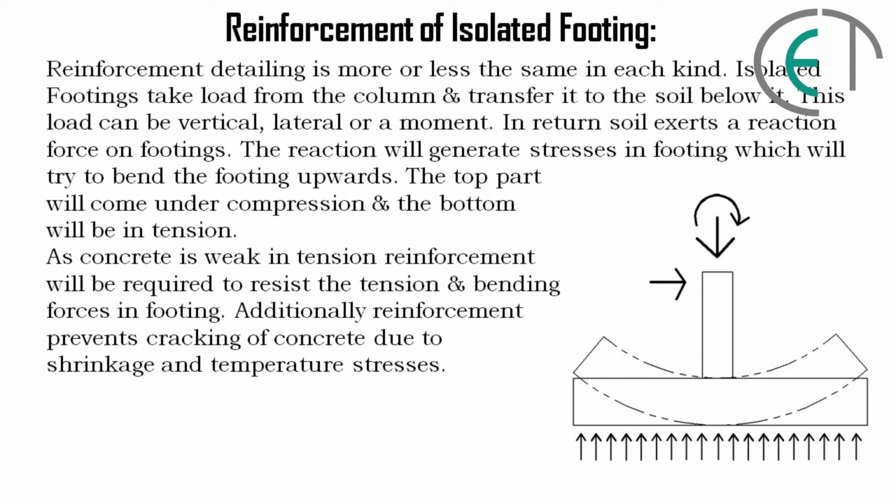The reaction will generate stresses in the footing which will try to bend the footing upwards. The top part will come under compression and the bottom will be in tension. As concrete is weak in tension, reinforcement will be required to resist the tension and bending forces in the footing. Additionally, reinforcement prevents cracking of concrete due to shrinkage and temperature stresses.